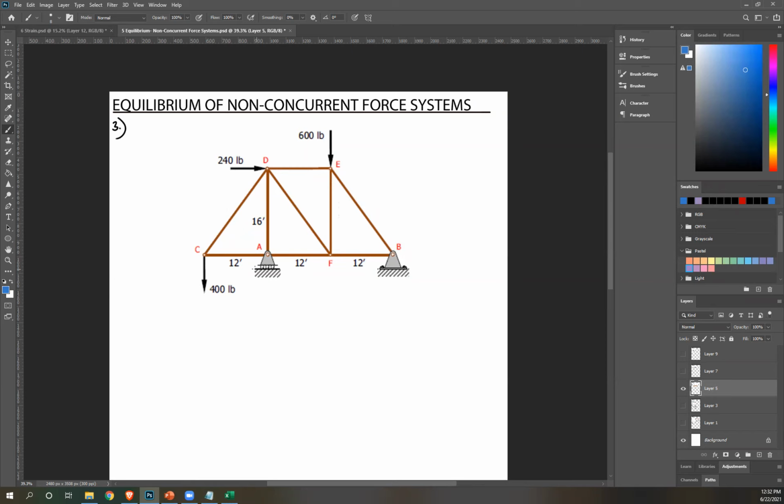Okay, so therefore this is the surface. So perpendicular to that, we have this. Let's call that RA. Once again, there's only one reaction there. Then at a pin, we have two reactions, one perpendicular and one horizontal. So this is perpendicular. Let's call that BV since it's vertical.